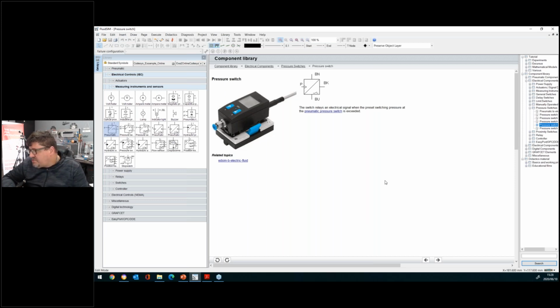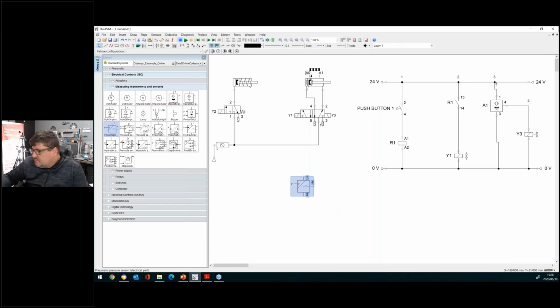All right. Any other questions? Yes, one guy asked, in the case of the filling machine that you demonstrated, how would you be able to stop the cylinder in any position in the center? Let's say 50%. That was one of the other questions. That means the position of the actuator. Yes, you must know that then we will utilize a 5/3-way valve with a mid position closed. Let me quickly explain it to you like this.